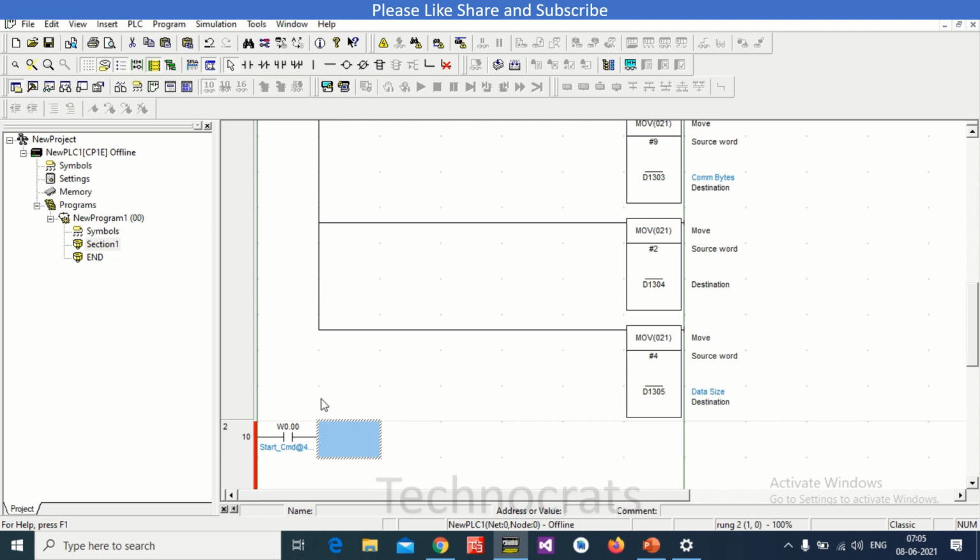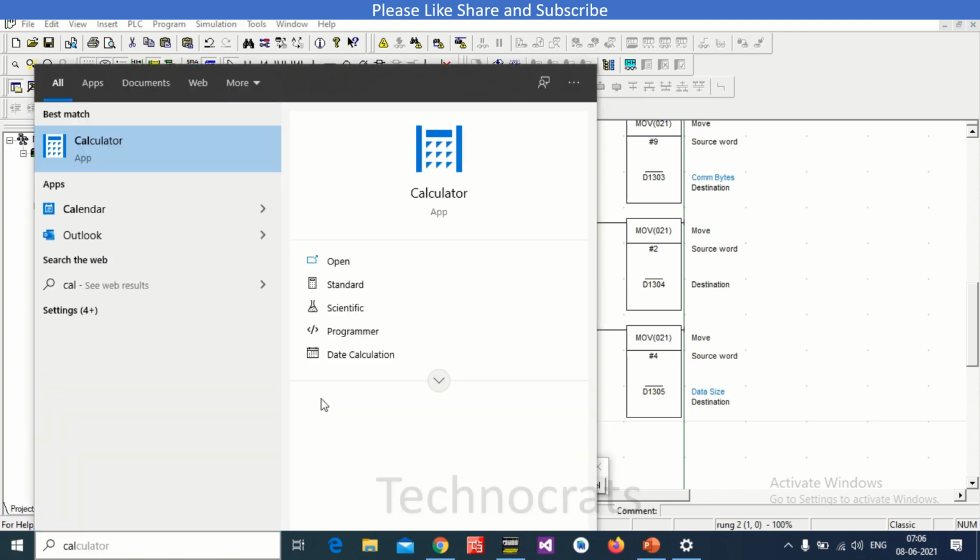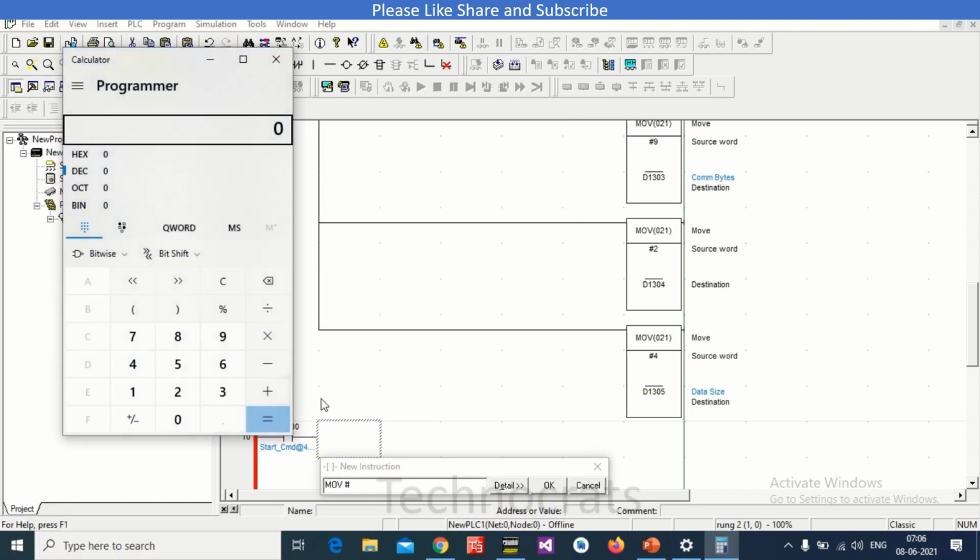Now what I will use is MOV #. Let me open the calculator first. In the first data word, that is your D1306, the first 2 digits will be your run command, that is 01 is your run command.